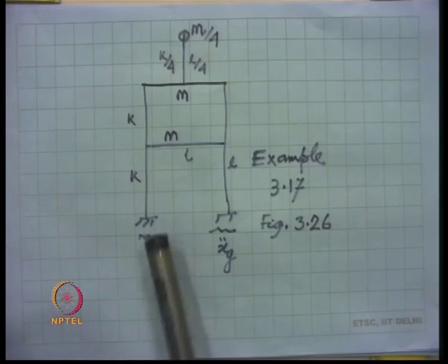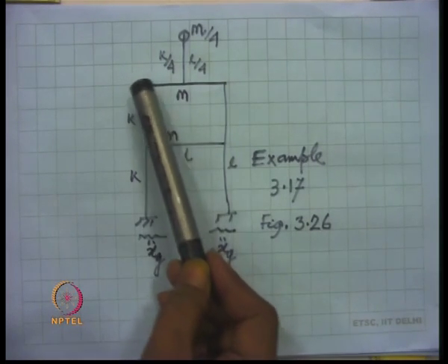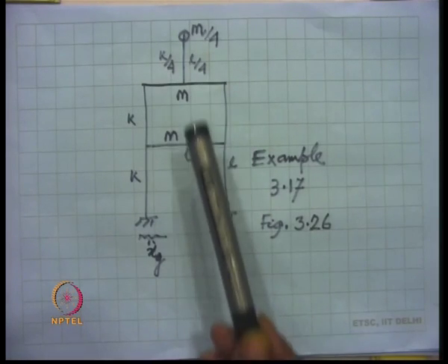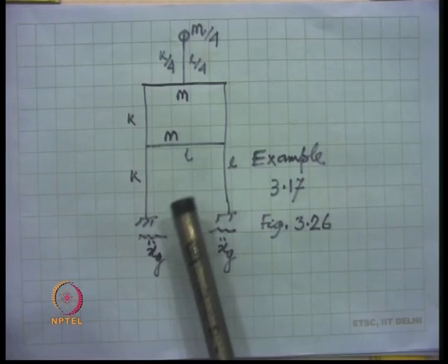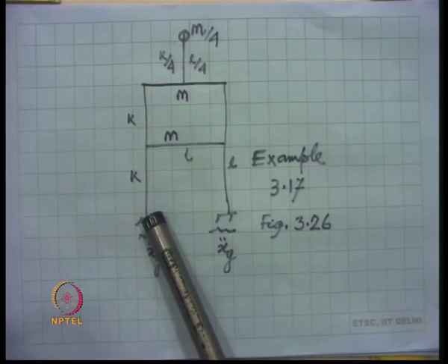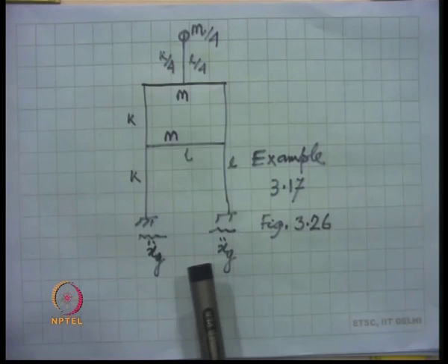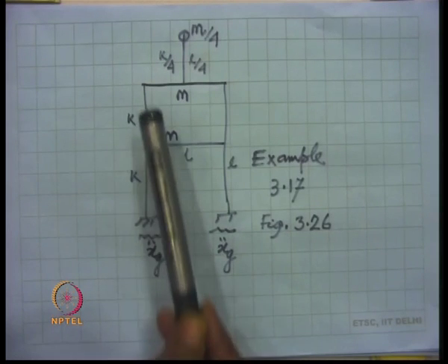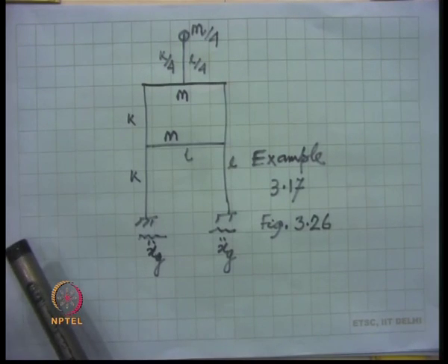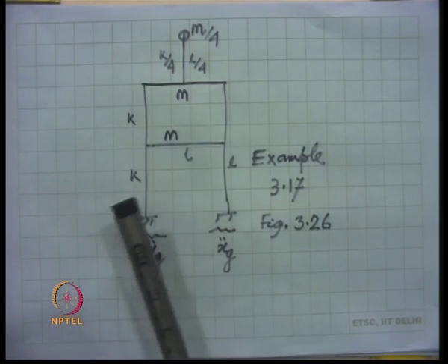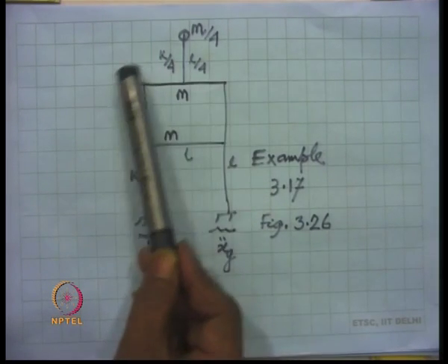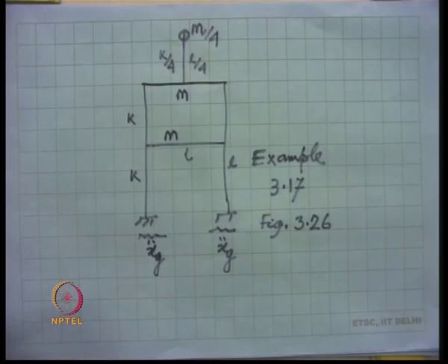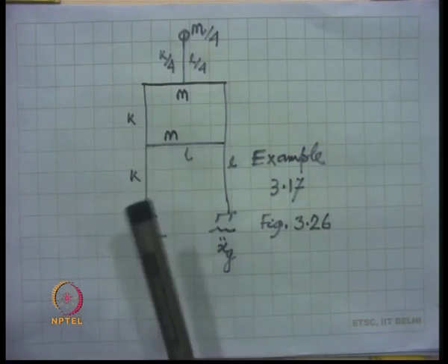For that, first we find out the time history of the relative acceleration of the top floor, that is, the relative acceleration with respect to the base, and to that we add the time history of the ground acceleration. So, that provides a time history of the absolute acceleration of the top floor. Then for that time history of absolute acceleration, we obtain a corresponding response spectrum of acceleration.